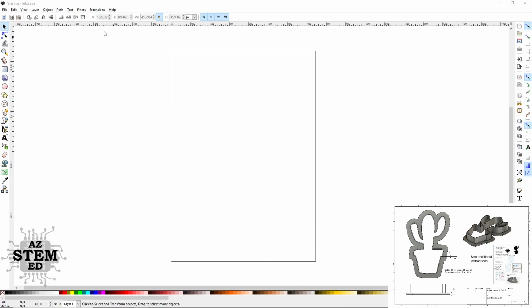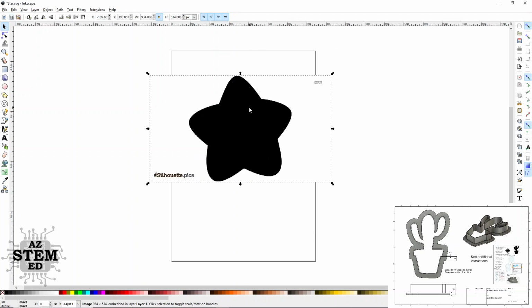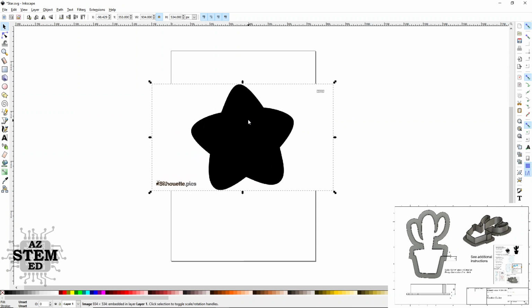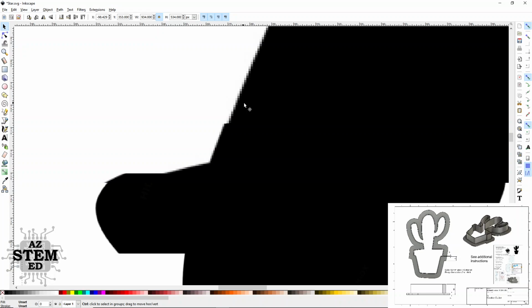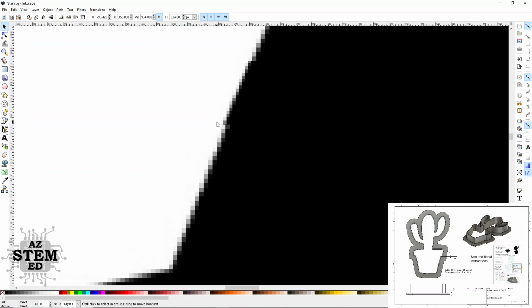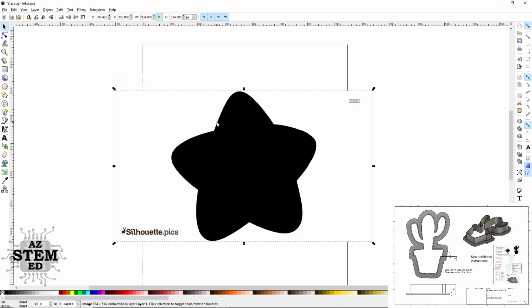This is in Inkscape. What we're going to do is just right click and paste, and it will paste the image that we have. Right now it's pixelated. So if we were to zoom in, we would see very big pixels, and it's not good for the uses that we need it. We need it to be an SVG and not a pixel. Okay. SVG is a kind of mathematical equation that maps out the very outside edge, and then it fills it, but it's not like this square and then that square and that square, like a pixel or a raster image.